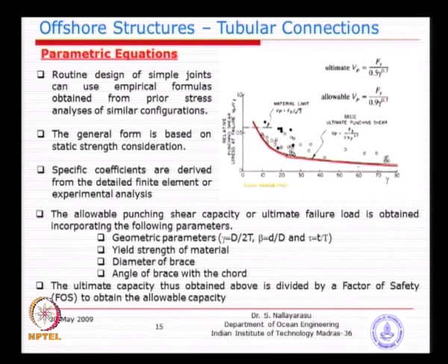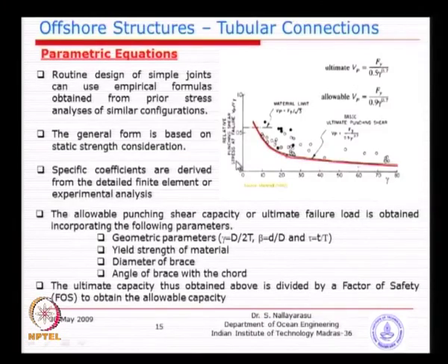So you relate the response to the parent variable by some relationship, and it is not necessary that you derive it. Basically in mechanics you normally derive. For example, for the bending capacity of a beam, you do not write it yourself, you derive it from first principles of simple bending theory. Whereas in this particular case we can't derive it because the behavior is so complex.